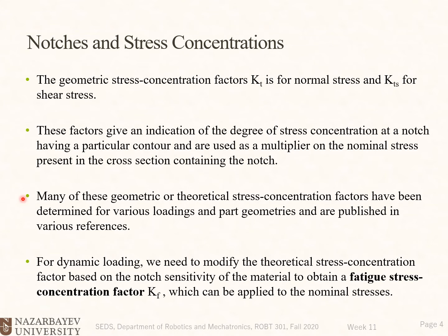For dynamic loading, we need to modify the theoretical stress concentration factor based on the notch sensitivity of the material to obtain a fatigue stress concentration factor Kf, which can be applied to the nominal stress. So what we need to do, we need to first calculate the theoretical or geometrical stress concentration factor, and then we need to take into account the notch sensitivity of the material.